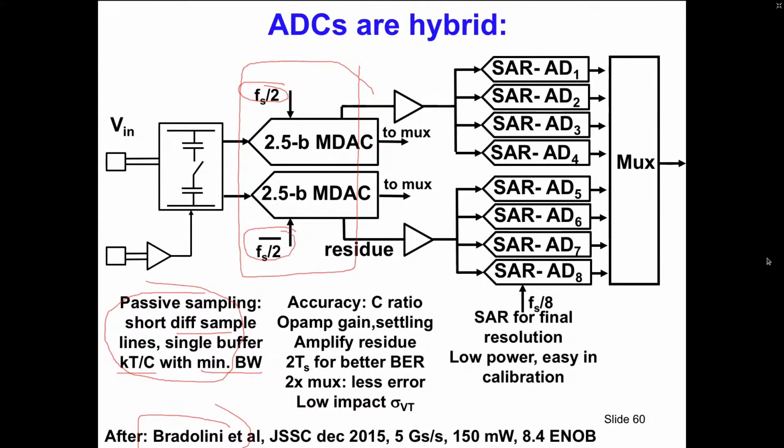Why is this optimum? That is optimum because a number of errors appear at half of the sampling frequency. And very often you're not interested in that because you're only interested in that range. If you would have 3 of them, you might already have components that fall into your range.